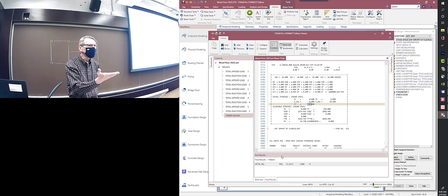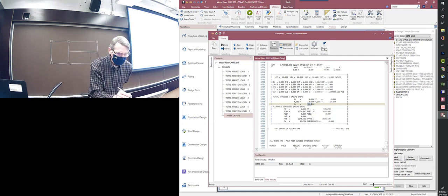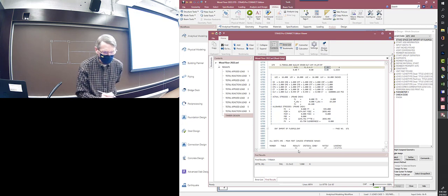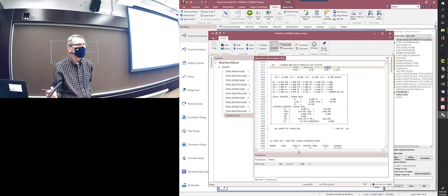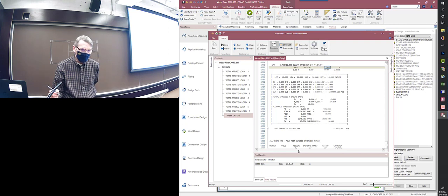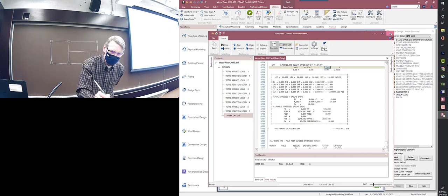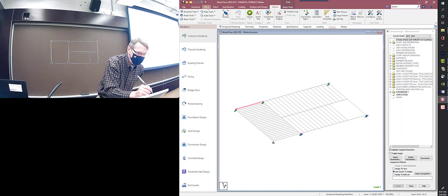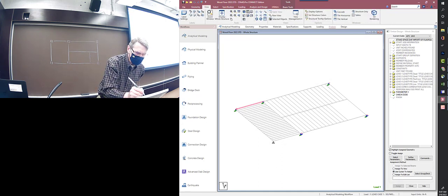And it seems like we did this Friday, didn't we? We noticed one that was failing and upped the size of it, if I remember right. That was probably that one. So you kind of remember 179, and here the ratio, you can see, oh yeah, it's only failing by 6%, right? So it just barely fails. So 179's got to get a little bit bigger. Other ones are maybe over-designed, but at least they're passing. So we could check. Let me get a view that I can see a little better.